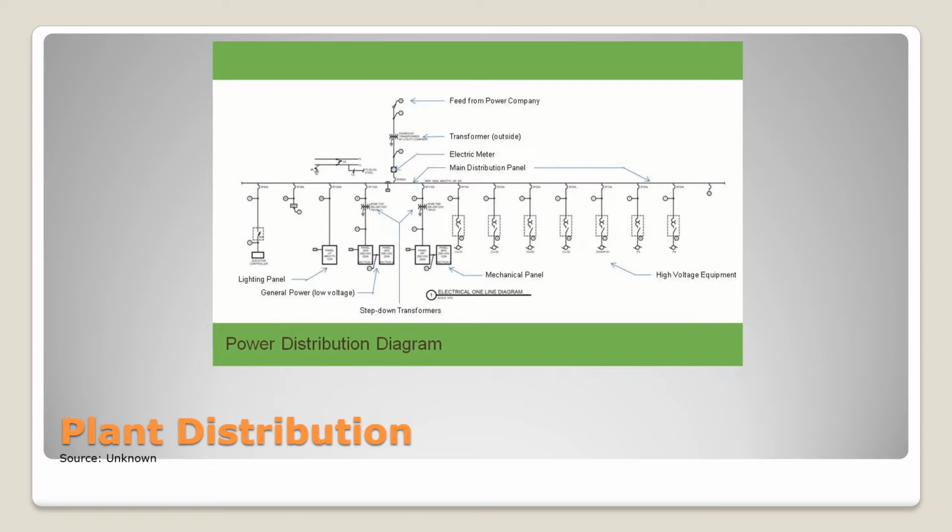It would be an interesting challenge to have 4,160 volt appliances. They would work just fine, but they would be huge because of the insulation required. So we reduce the voltage, increase the current, and are able to reduce the insulation as a result.